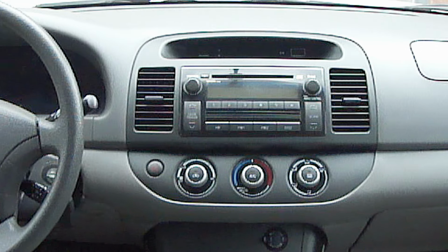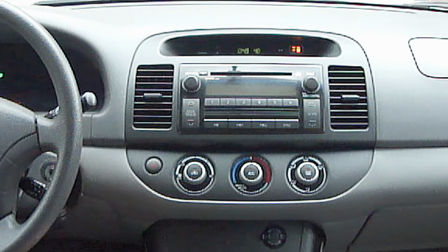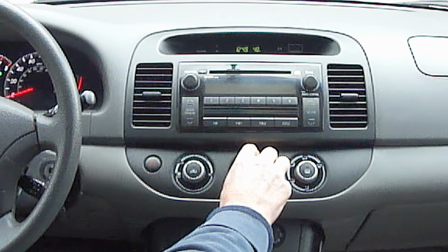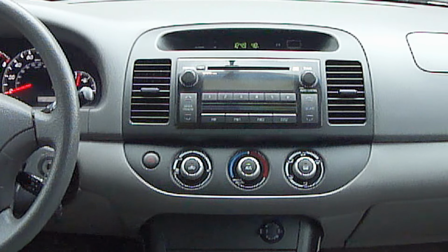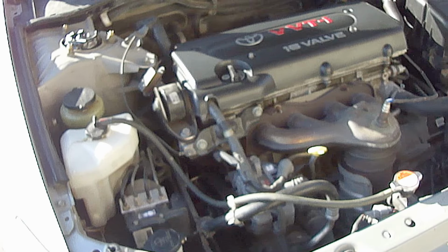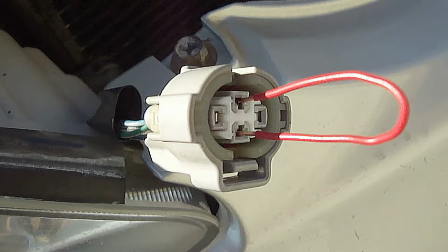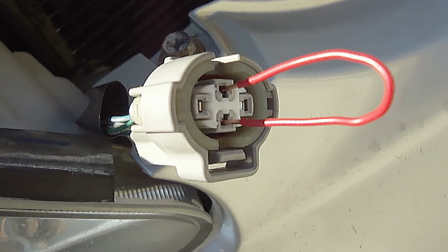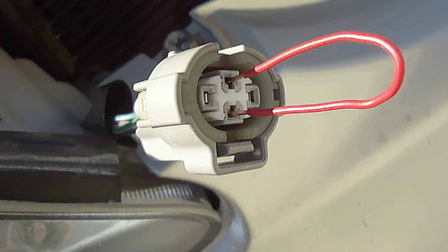With the pressure switch electrical connection disconnected, start the vehicle. Next, turn the air conditioner on maximum cool with the blower on high. You'll also want to lower all the windows or open all the doors. As you can see, the clutch is not turning. As you can see, by placing the bypass wire ends on these two electrical contacts, which were the correct combination, the clutch is now turning.